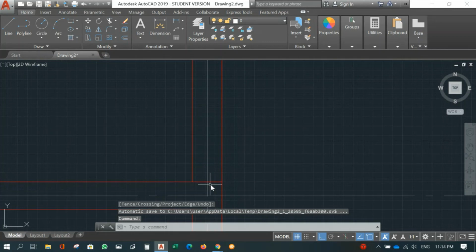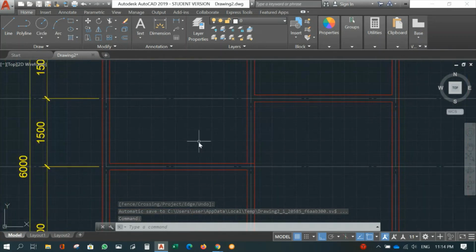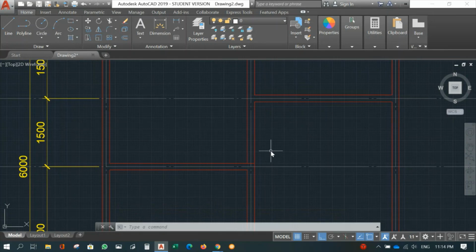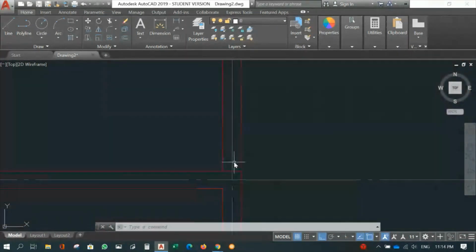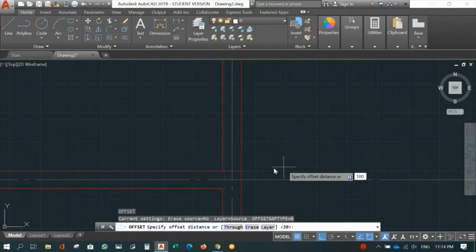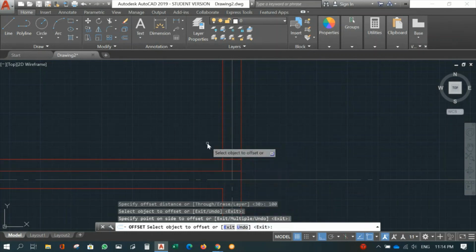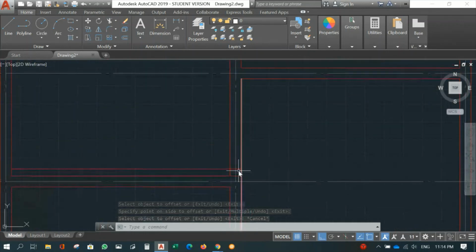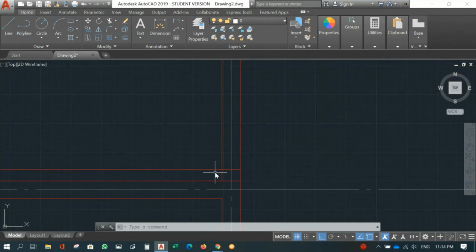So first thing we need to get the size of the door swing, right? So the size, it could be about, we can actually increase this about 100, right? Offset 100 or 50 also can. Okay. It means that the door will begin here. Okay. Why we need to use this? Usually sometimes at the back of the door there is things like something that we need to hang, right? So at least there's 100 space between the wall to where the beginning of door jamb, then we can have space there, right?